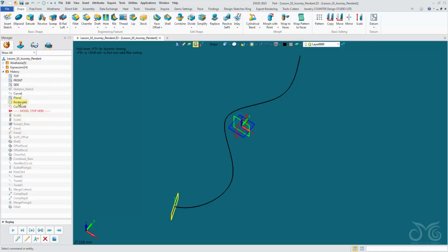Also in the right click option panel we can suppress. We know what the suppress does. We can cut, copy, paste, delete our operations. So we can move our operations within the history from place to place. We can copy them. This can be useful. It allows us to move operations prior to one another or after one another without having to re-perform those operations.